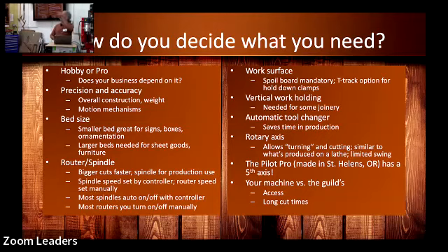Vertical work holding, we meant, yes, Craig? I just wanted to make a point that one of the scariest things that happens on the CNC, and probably everybody will see it happen at some point, is if your piece comes loose. Yeah, it is so scary when you've got a router turning at 15, 20,000 RPM. The hole that you're going to make is supposed to be a half inch and it ends up being, it just is one of the scariest things. Yes. So it's really critical to hold it down solid. Dave uses screws. Yes. We'll talk about the different hold down techniques, a variety of them.